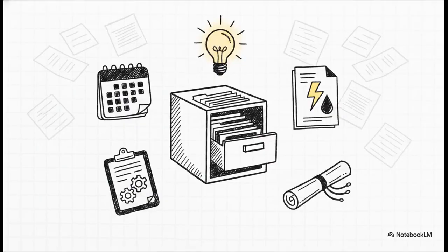If you are a CSR team member or a plant manager, I highly recommend you screenshot this readiness list. To do this right, you need 12 months of electricity and fuel bills to show those seasonal variations. You need your production data, complete equipment lists, and past maintenance records. And I gotta warn you here, a messy data room severely reduces the quality of your final audit.